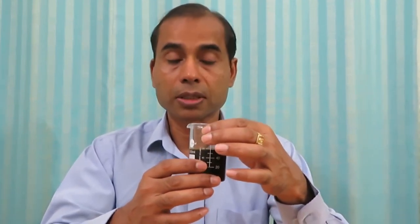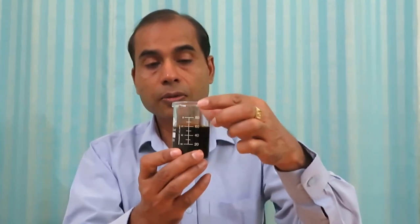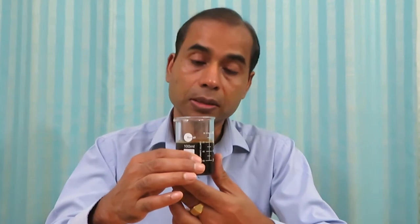Now one more thing I would like to show you is the oil after it has been used in an engine for about 5 months. So this is the same oil after 5 months of use. You can see that this contains a lot of blackish things, and these are the degraded or oxidized different organic molecules. It contains soot from the engine, and it also contains some wear particles.